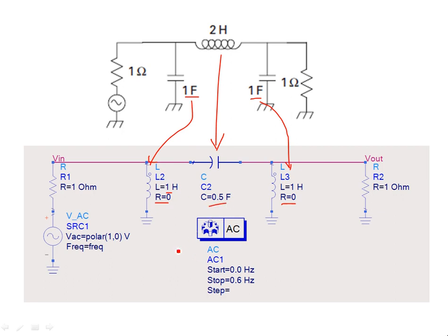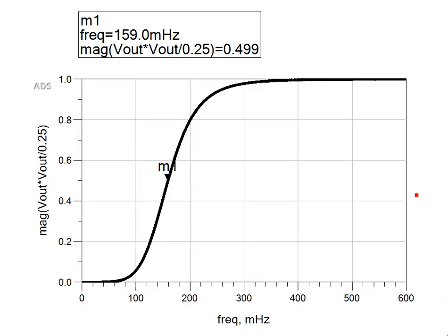Now if you do this simulation, this is for a low pass filter because this is generic, right? And the response is that of a Butterworth filter. This is not a Chebyshev. So you will see this is the magnitude response. It's not in dBs, and it's a normalized magnitude response because the maximum scale is 1. It has been normalized with the maximum output power. This is the power response.